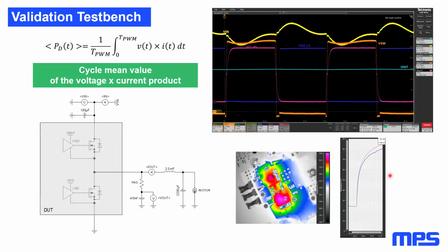To confirm this hypothesis, we have also compared these average measurements done with digital multimeters with the average power computation done on actual current and voltage measurements done on an oscilloscope. With a thermal camera, in the meantime, we have kept under observation the junction temperature, taking care to record the results only when the system has reached its steady state.